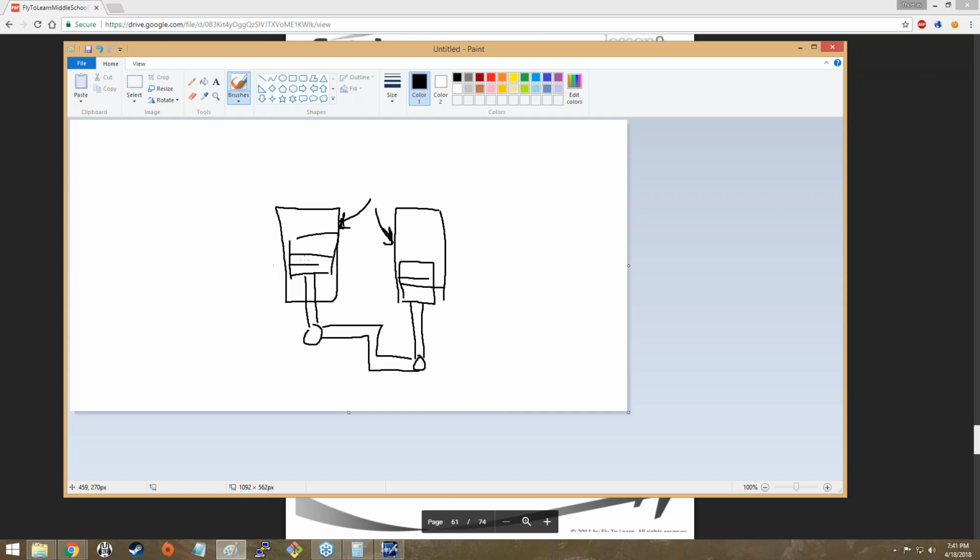But here's the deal. So this piston is moving upwards, right? And as it moves upwards, this is a poor drawing because this is actually a lot more airtight than my drawing would suggest. The air starts to get compressed, squeezed more and more. And as it gets squeezed, because the pressure is increasing, it's actually increasing the heat of the air as well. Eventually, the air gets so compressed and so hot that the fuel in the fuel and air mixture explodes. And then that explosion forces the piston back downwards. Because these two are connected, that forces this piston upwards.